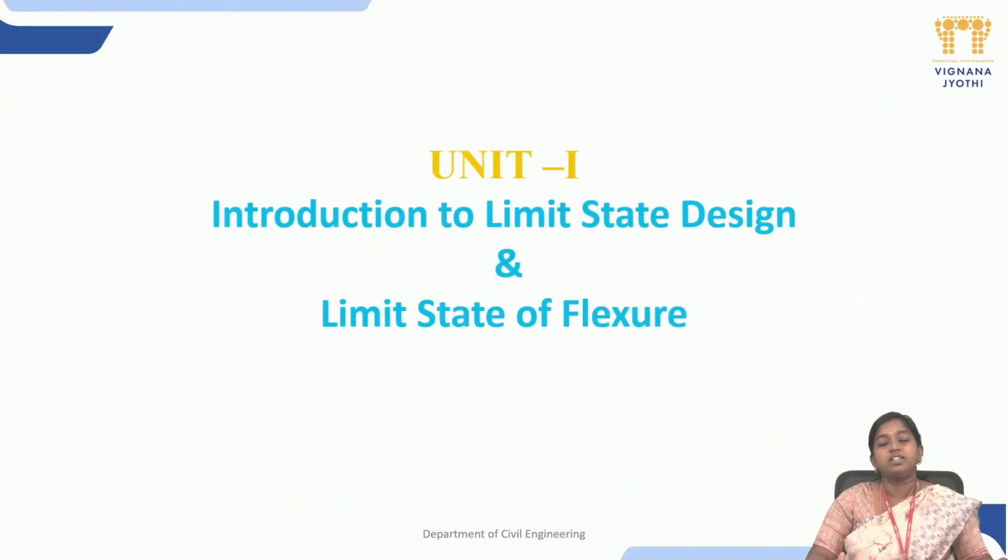Firstly, the first element that we would be seeing is beams, and we will be dealing with the limit state method, which is divided into two parts: limit state of collapse and limit state of serviceability. Limit state of collapse deals with forces, moments, and torsion, and limit state of serviceability especially deals with deflection, cracking, and vibration.